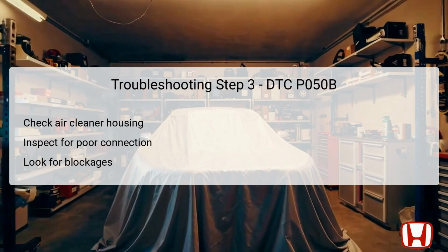It's important to examine its integrity thoroughly, as any issues here can affect engine performance significantly. If the housing is found to have defects like cracks or other damage, it should be replaced to restore optimal function. Only if this component is confirmed to be in good condition should you proceed further in the diagnostic flow.